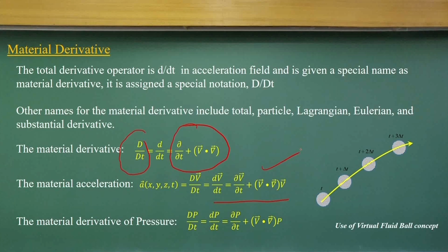Okay. So, that means at the particle level, how it varies with time, it has two components in the Eulerian frame. One is the local component, another is the convective component. The gradient we have represented like this is a particle derivative. That means it is the derivative for the particles as they are moving. Material derivative, particle derivative, all are the same.